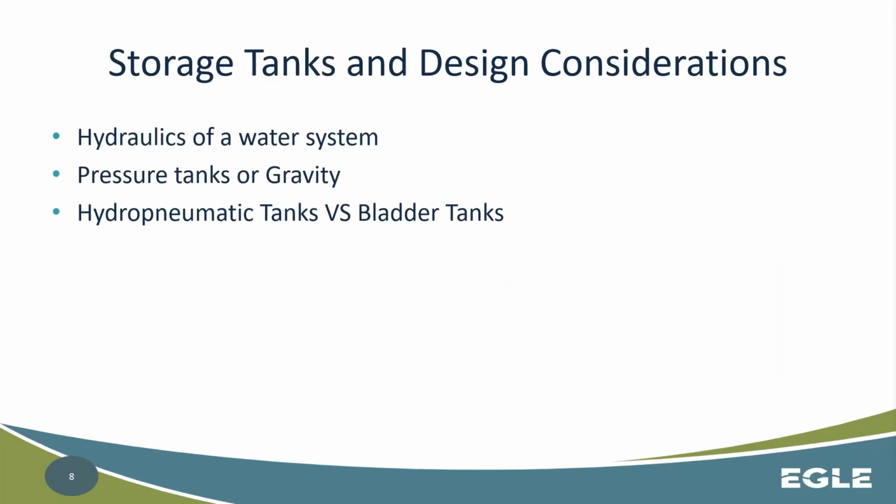Storage tanks and design considerations. So what's the normal hydraulics of the water system? Is it high pressure districts? Is it low pressure districts? Is there abnormal topography? Is there large demand from an industrial area, or is it mostly residential? All these things can go into what makes up your system.